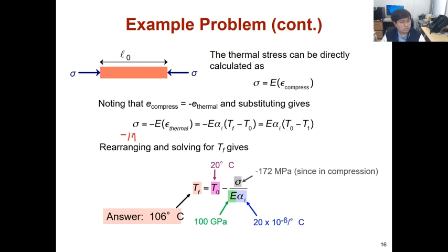So in this way, we finally obtain the result. Maybe 170 megapascal, 10 to the 6 pascal, and for brass the Young's modulus we should check, 100 gigapascal, 10 to the 9 pascal, so that we can cancel out the alpha. Before we start, we should know that the alpha coefficient here is 20 times 10 to the minus 6 per Celsius or Kelvin, similar.